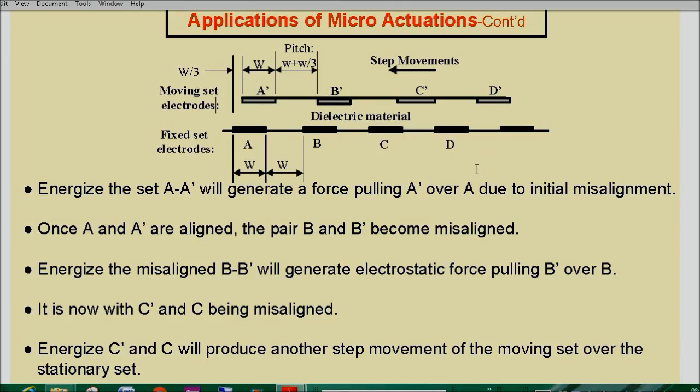And these electrodes, of course, have a length, and for this length we use W, not L here, because we are talking of producing the force which is in line with the plane. The equation that we are going to use is FL, which uses the width of the electrode. So for that reason, the length of this electrode is now given as a width W, because W is used in the FL equation. So we are calling this electrode as having the length W.